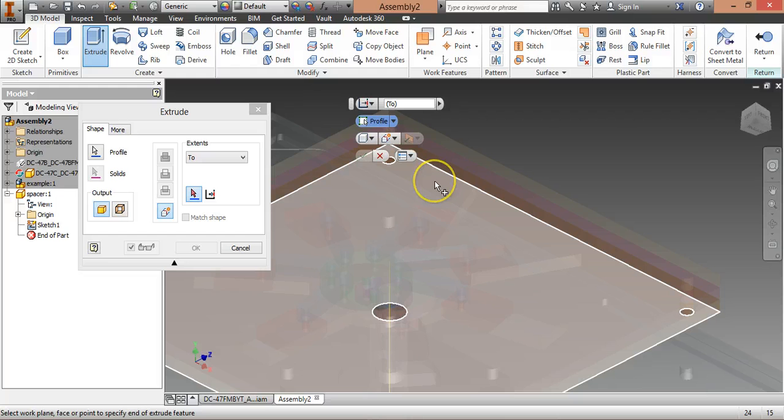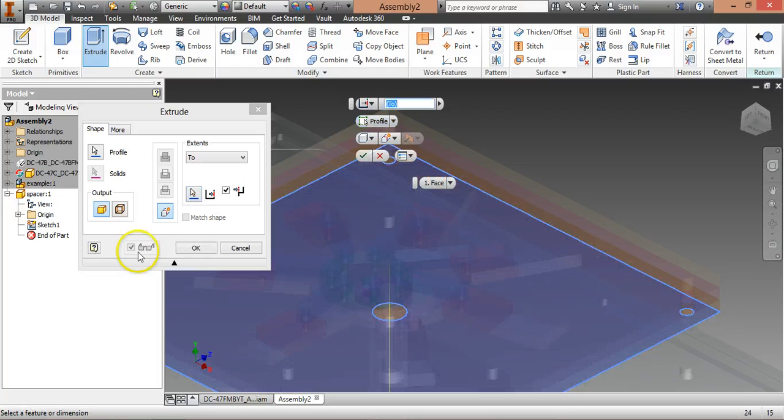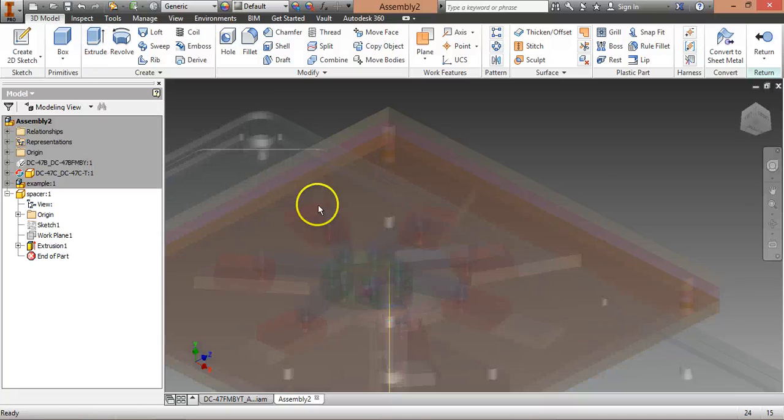And in this way I can create the length of the spacer appropriately without ever having to measure anything. And then in the end I can measure the component that I created to know how long I will need to cut these spacers when I actually assemble it in real life rather than on the model.